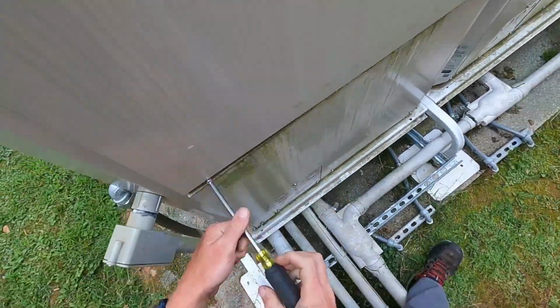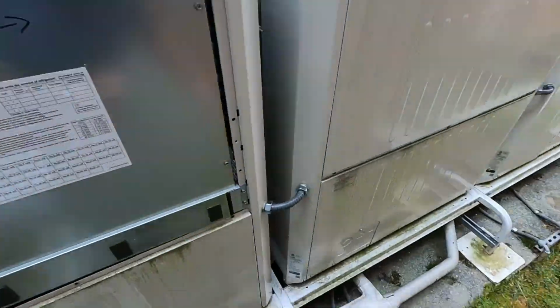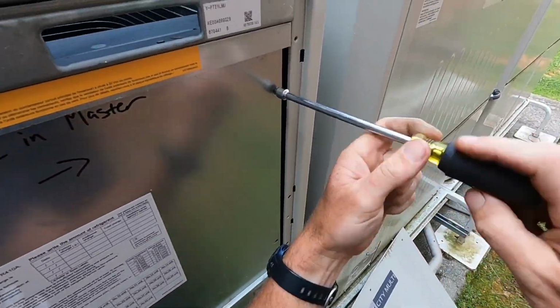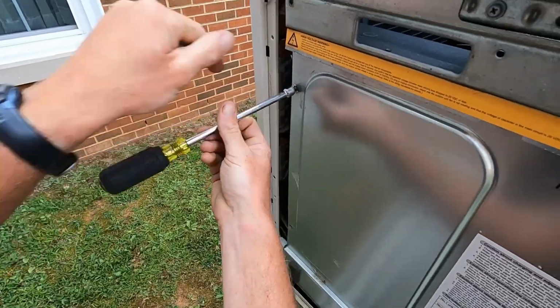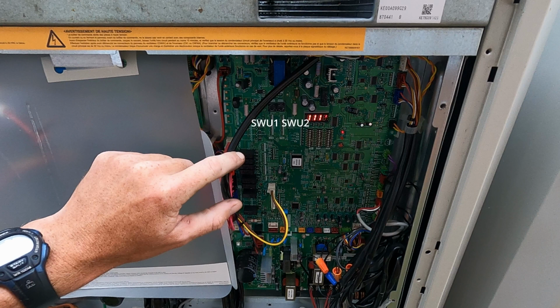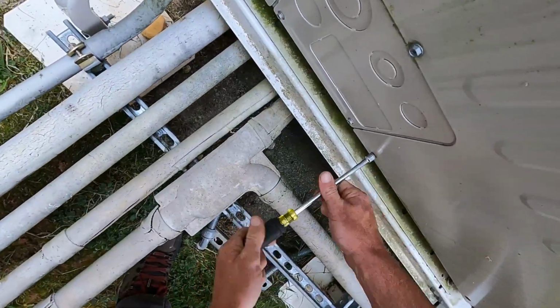I already know where the outdoor unit with address 53 is physically located, but if you weren't sure, you could reference the model number in the top window for that unit in the status monitor and match it to the nameplate of the physical unit. The address is also denoted on the main printed circuit board in each outdoor unit by the address dials, often labeled SWU1 and 2.